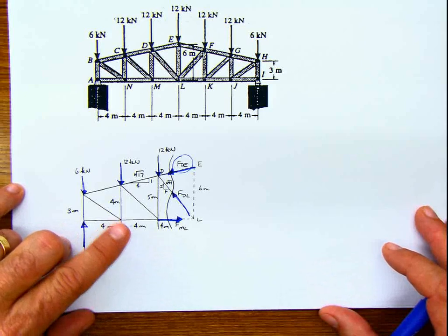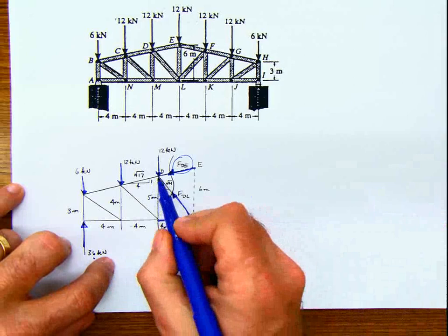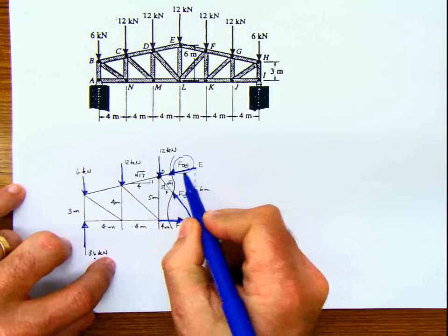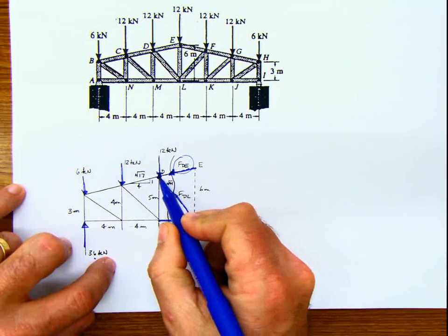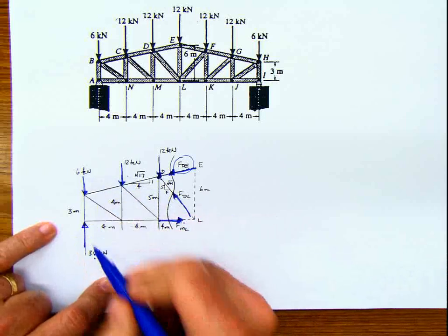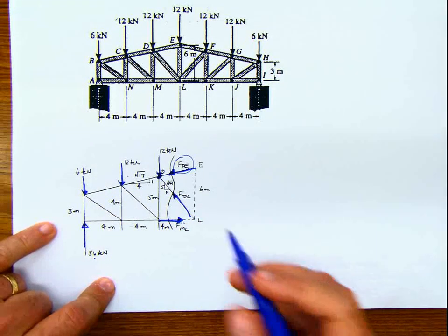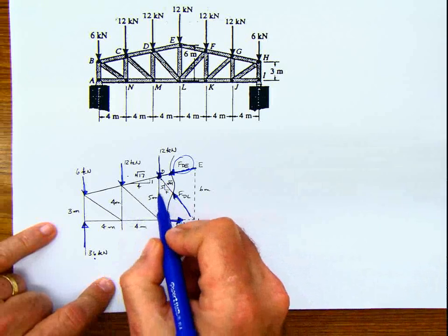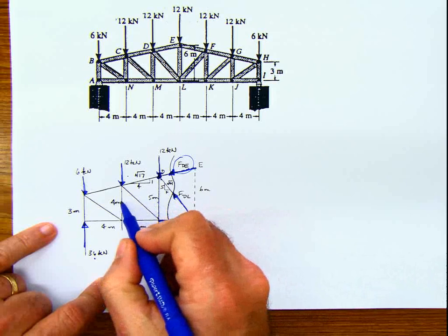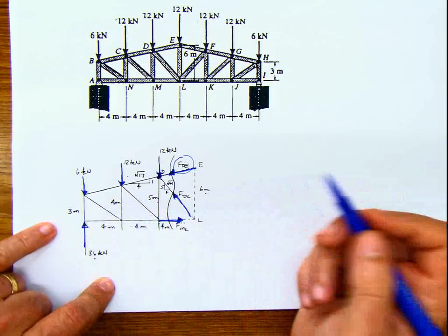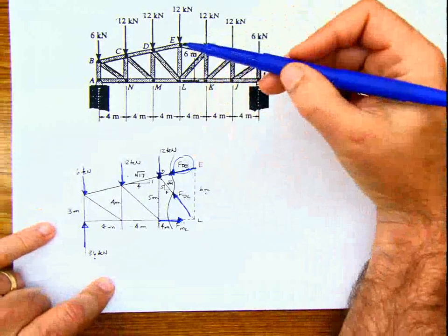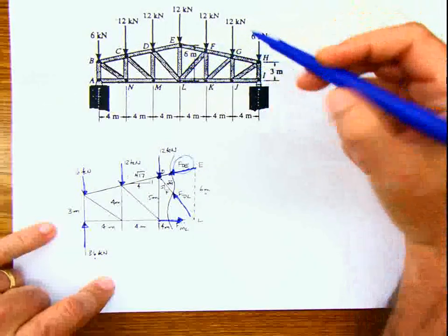How do you start solving this problem? Well, it's easy. If I do summation of moments at D, this force and this force are not producing moment whatsoever with respect to the point D. The only forces producing moment are force ML, this 12, this 6, and this reaction. So let's do that. But in order to do that, I need to know how much this height is from here to here. I said it's 5, and I said it's 4, and I said it's 3, yeah, and this is 6. How would I say that? Well, remember the only information that you have, the only data that you have is this is 6, and this is 3.